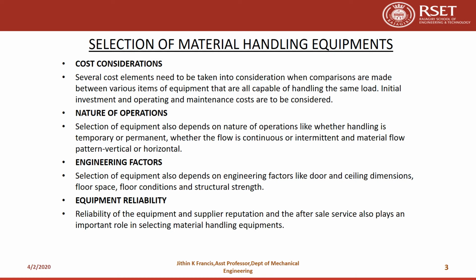You have to consider your floor space, door size, and floor condition and strength before selecting handling equipment. And the last factor is equipment reliability. The reliability of the equipment, the supplier's reputation and after-sales service also play an important role. Suppose a handling company offers you equipment which is unreliable or does not have service in your factory space, once its lifetime ends, you cannot repair it or even carry out a maintenance activity. So these factors also have to be considered while selecting material handling equipment.